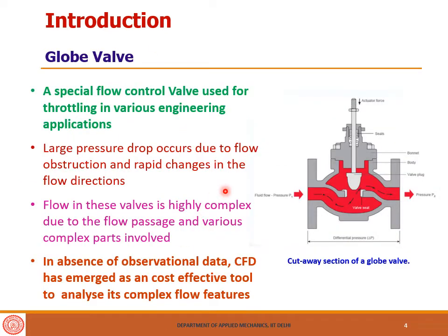Now talking about the globe valve, it is a special kind of flow control valve which is used in a wide variety of engineering applications. The name globe valve is because of the shape of the valve, which is hemispheric in shape. Large pressure drop occurs through the valve because of sudden restriction in the geometry, so this gives rise to